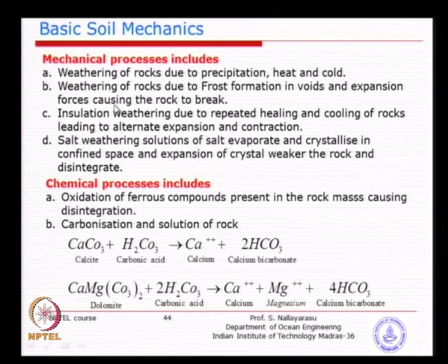Mechanical weathering is the predominant form of forming particles of various sizes. Chemical weathering occurs in very isolated places, basically due to carbonation or oxidation of ferrous compounds present inside the rock. During oxidation it becomes oxide and becomes porous, then the rock breaks.